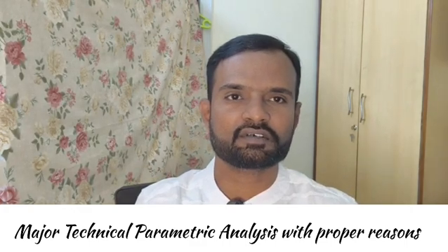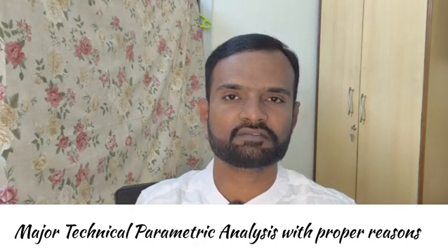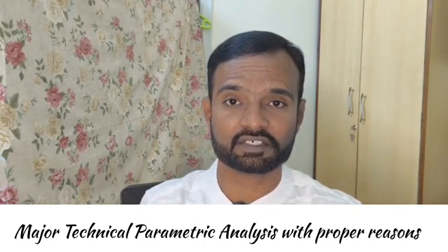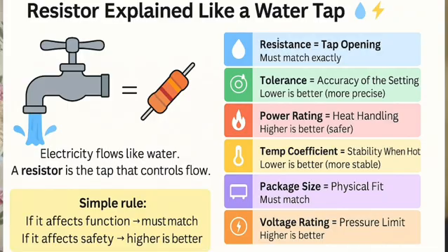Let's understand, on the side, a little more about technical parameters. For resistance value, by default we should select the same resistance value when recommending a new replacement solution. For tolerance, lower is always better, because it is more precise and will not deviate in resistance value even when there is a high flow of current or voltage within the circuitry. For power rating, higher is better.